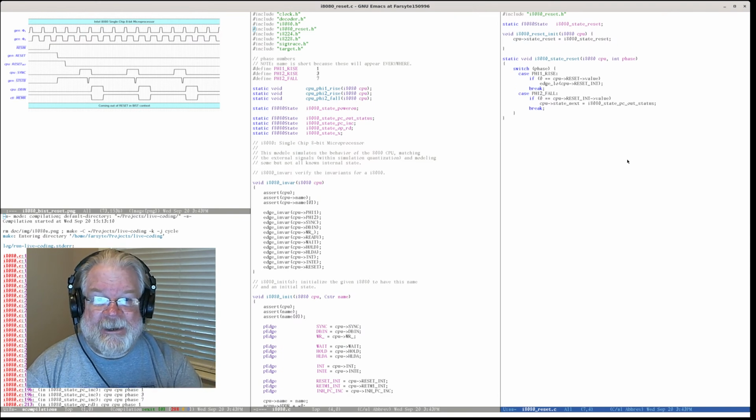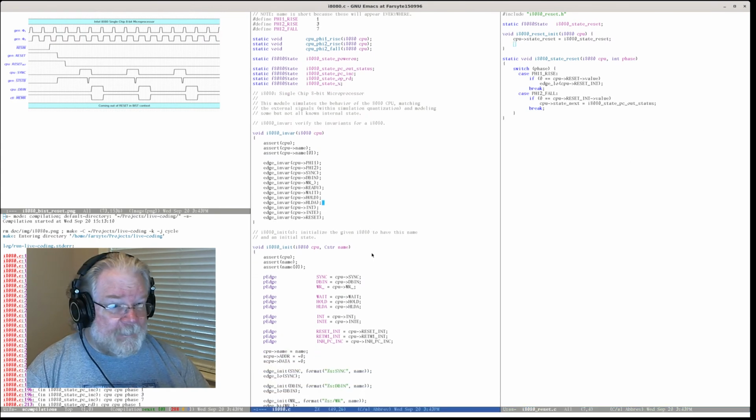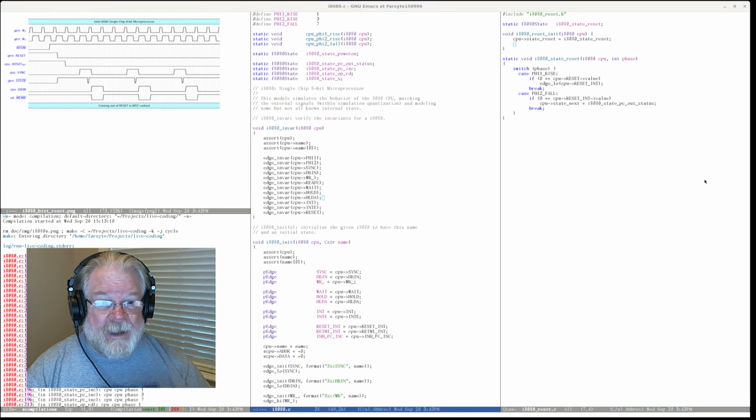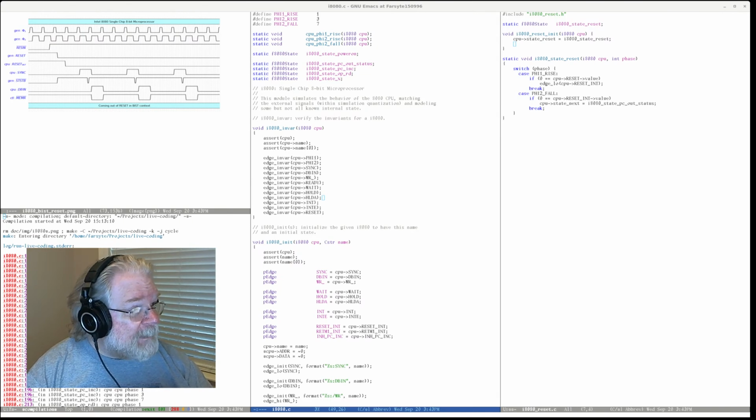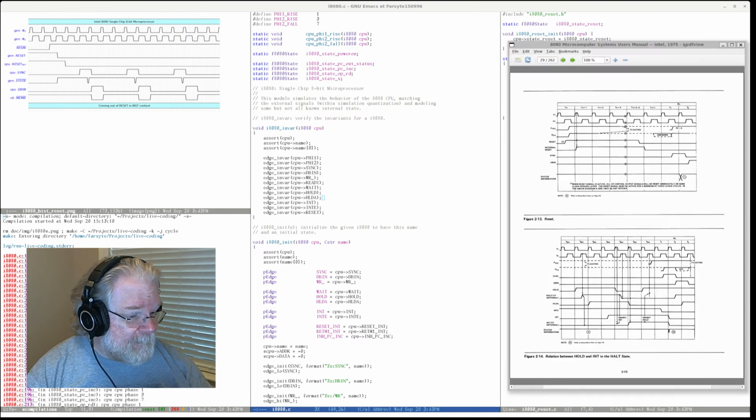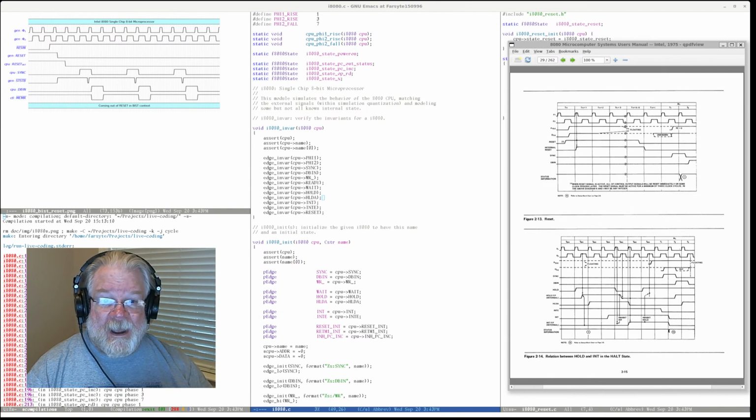And then we're going to say, well, let's see. If anybody turns on reset, let's take a look at the diagram again. There's this whole left half on the diagram that I didn't point out before. This is going into reset. So if reset signal goes high here, internal reset's going to go high here, and we need to be in reset. So when this goes high, we need to have address and data floating and so on, and this needs to happen immediately.